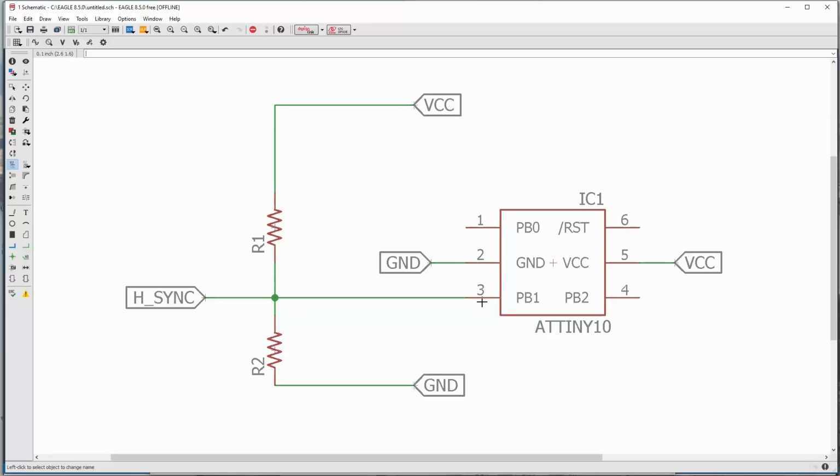So what we do is we say, okay, well, we want 0.3 volts. So we have a voltage divider, so we basically go only 0.3 away from ground, but 4.7 away from VCC. So we could compute this, or we could just cheat and use a potentiometer instead of this voltage divider here. So that would look like this.